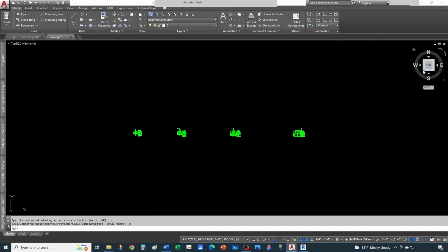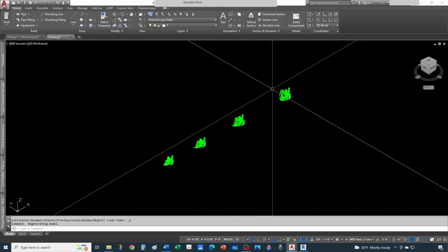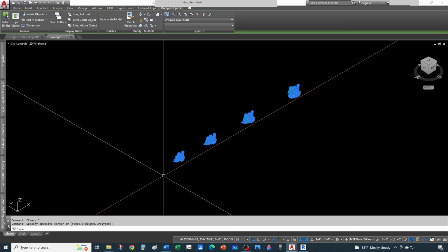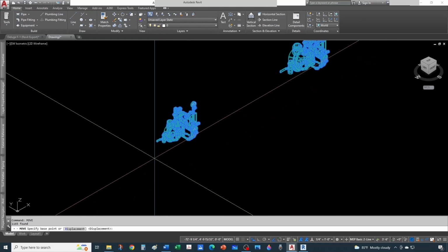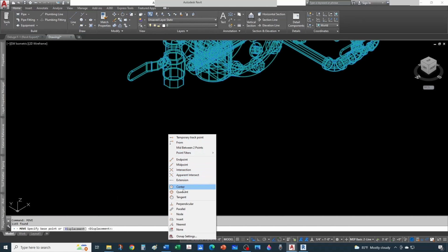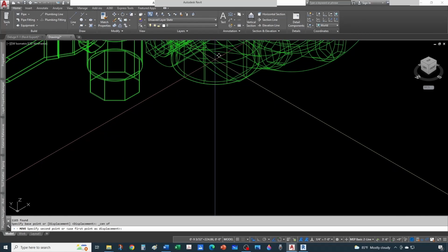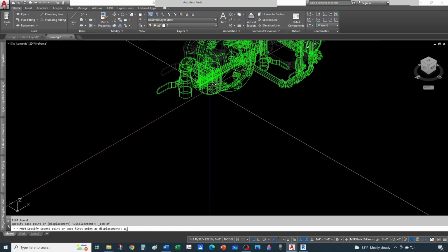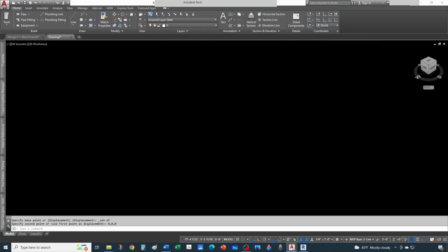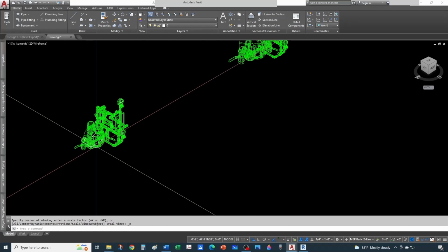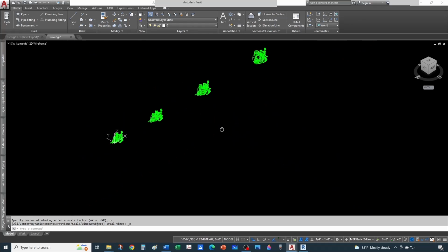And then one thing I like to do, and this is not necessary at all, is I select my smallest family, and then I move it from a representing point like the inlet of the valve to 0, 0, 0. That's just my nature. I like to have things with a certain origin, but this is not necessary.